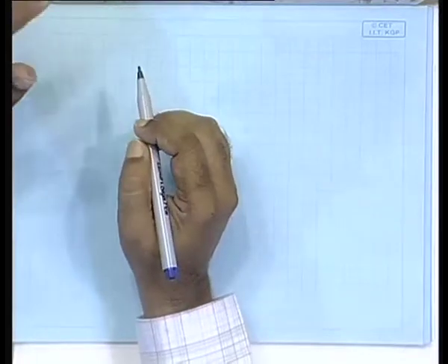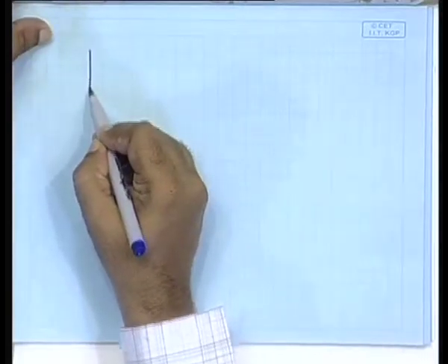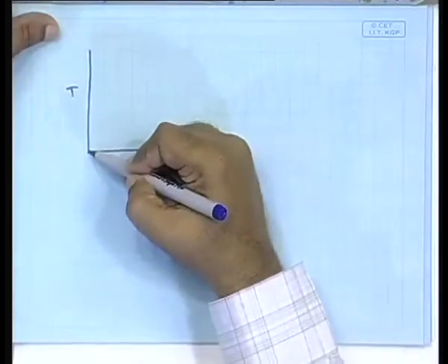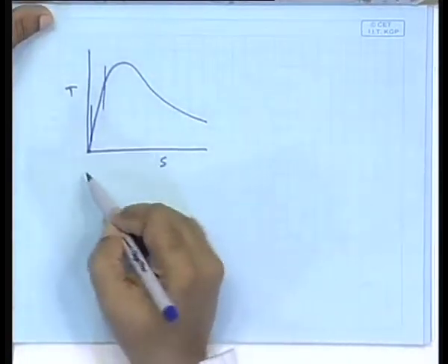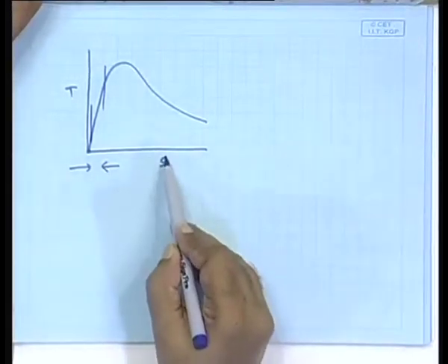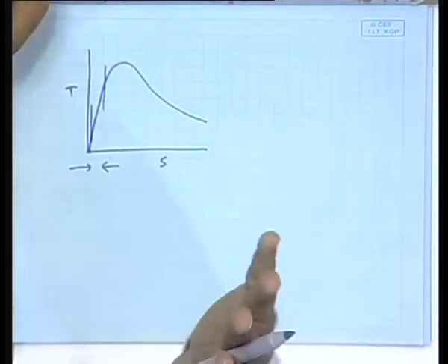firstly, if you connect it directly to the grid, then yes, at least logically, theoretically, it does supply a constant frequency, though it can rotate, but actually it cannot because of the torque slip characteristics of the machine. It will be like this, and because it can operate only in the small range, it will have only a very small range of the slip that is feasible, and since slip is given by the speed, only a small range of speed will be feasible. So, the machine will be able to operate only within a very small range of speed variation. So, that is for the grid connected.